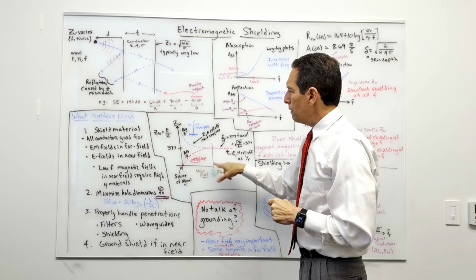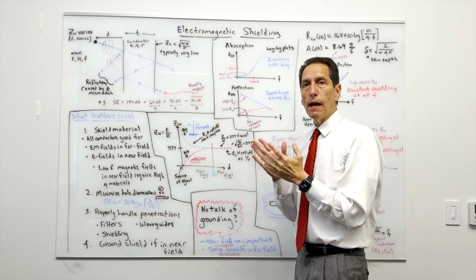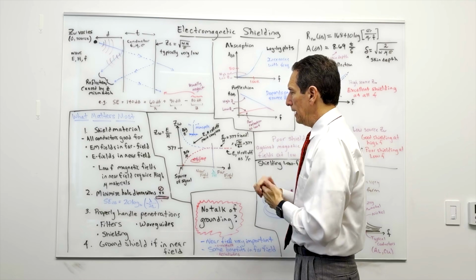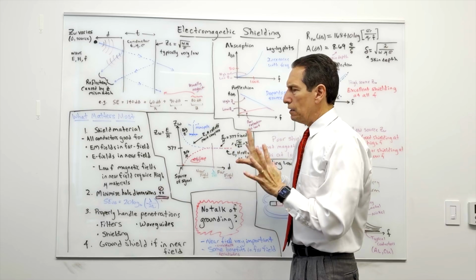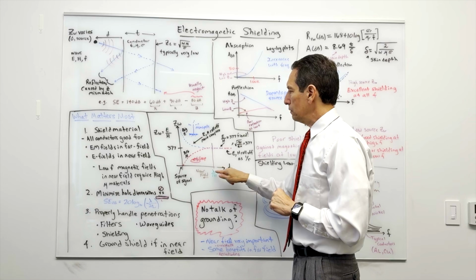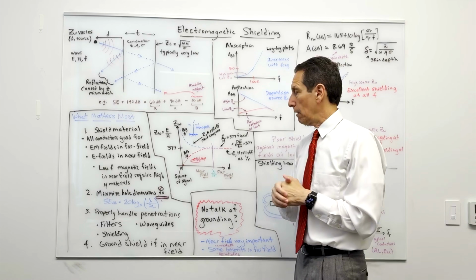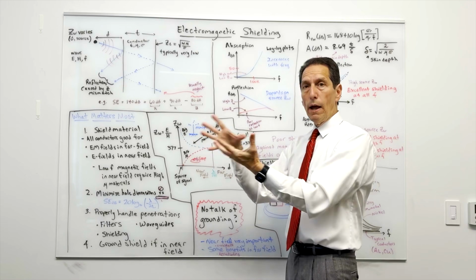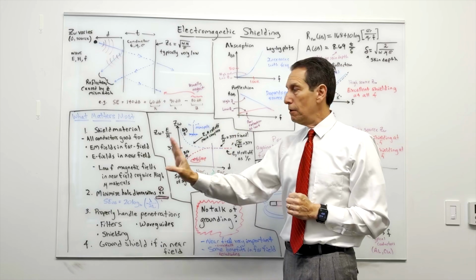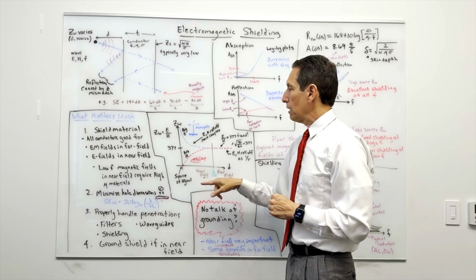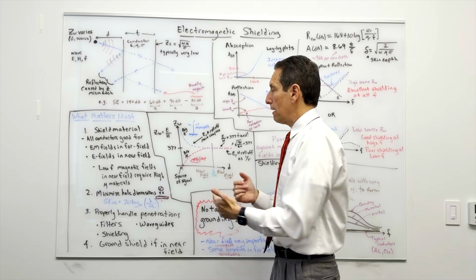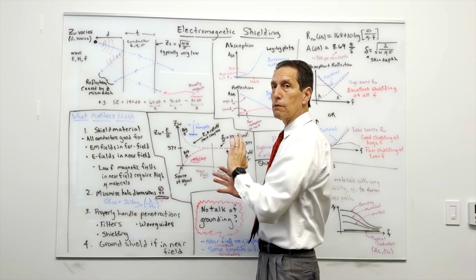Now, where do we put the line that says, hey, they've come together and this ratio is 377 versus they're very, very different. One dominates or the other dominates. And to simplify it, and there's a little more to it, but I'm going to simplify it, we'll just put a line at essentially the wavelength divided by 2 pi, all right? The wavelength of the incident wave divided by 2 pi, we'll let that be a number. And if we're closer than that number, and this is measured in meters, we're going to say it's in the near field, and that's where these effects happen. The antenna type really matters. You end up with a lot of magnetic field or a lot of electric field.